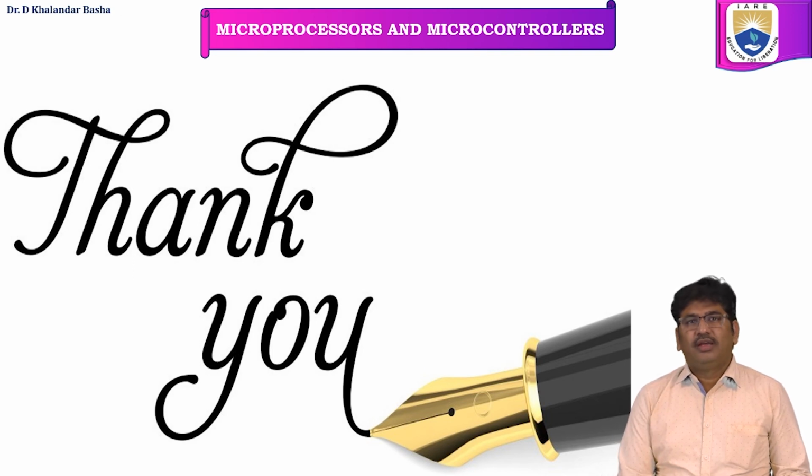Thank you all. In today's class, we have seen data communication, the various types of data communications like serial communication, parallel communication, followed by synchronous communication, asynchronous communication, the data format for asynchronous communication, introduction to baud rate. Next, the serial communication support in the 8051 microcontroller, the various SFRs corresponding to serial communication in 8051 are SBUF, SCON and PCON register.